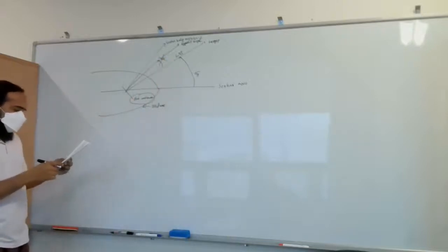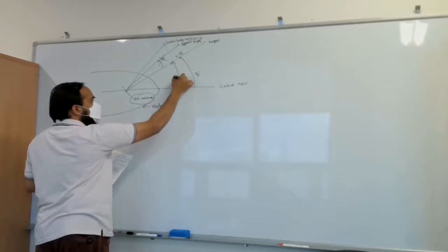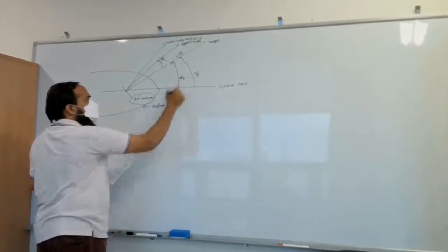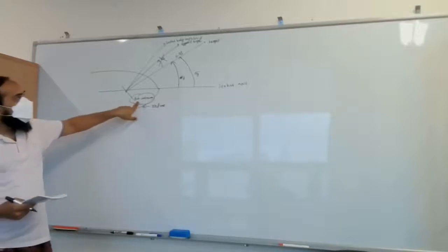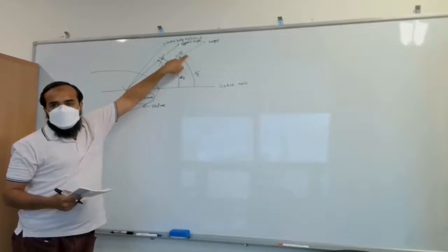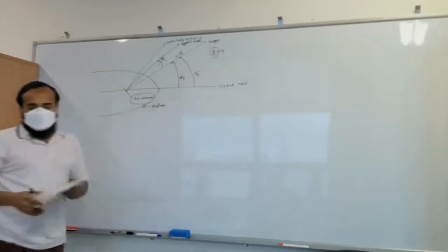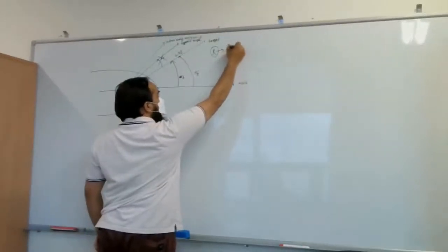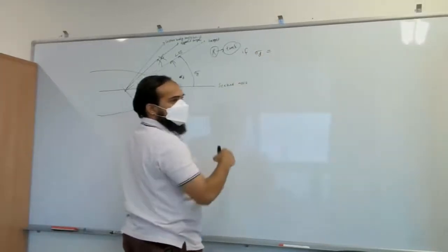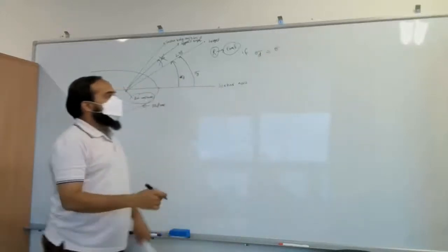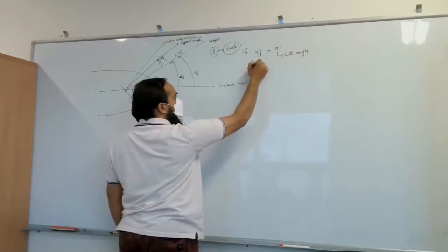There is also the angle of the dish antenna. Okay, dish angle. So without random effect, we want to make the rate of the dish antenna angle equal to the line of sight, so that we can track the range. Okay, so the range can be tracked if it equals the line of sight angle, right? This is the line of sight angle, and this is the dish angle, right?